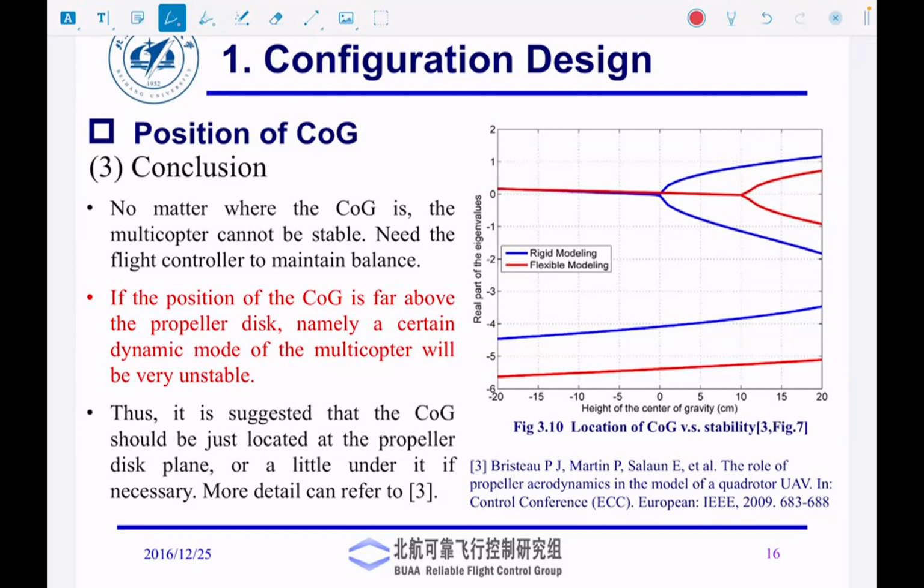Now, the question here is whether stability is good or bad. On the other hand, if you look at the design for the F-15, F-16, or fighter planes, those planes are designed to be unstable. Those are inherently unstable. Why? Because you want those planes to maneuver very quickly. If you have a stable aircraft, it's not going to maneuver very quickly. If you have an unstable aircraft, maneuvering is very easy. That's why fighter planes are designed to be unstable, but then they have an active control system that is controlling the behavior.